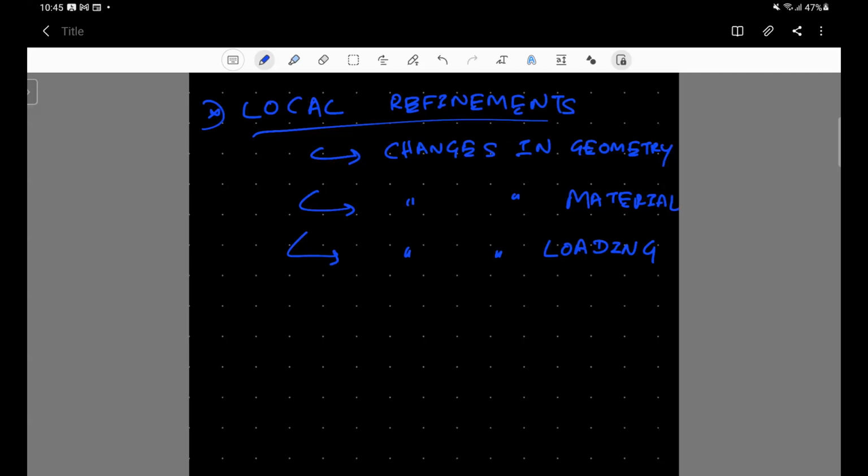It's always nice to use different element sizes, and elements having different aspect ratios, to see whether your solution converges. You can change the number of elements, meaning the number of nodes, and see whether you get improved results.